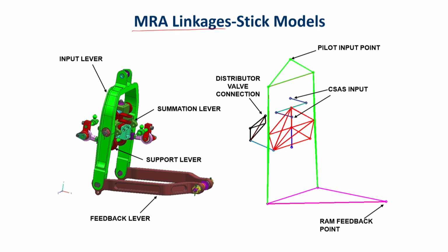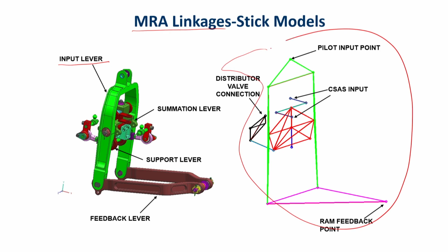So, you will be having all these things like the input lever. This is actually carrying the command of the pilot, and then from the input lever, as the command comes, there is a complete kind of complex linkage system that allows this command in terms of certain displacement or the load to be applied on the main rotor in terms of increasing the RPM of the main rotor or the torque of the main rotor, and then the feedback lever actually sends it back, and accordingly the whole system moves and the pilot takes a decision.